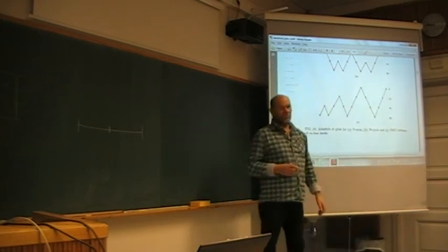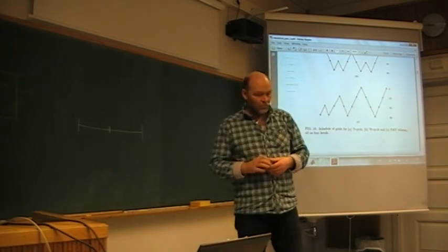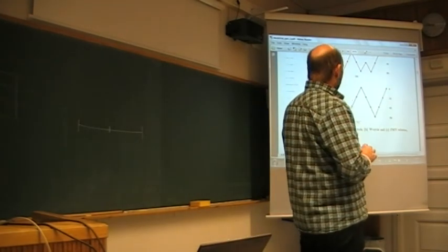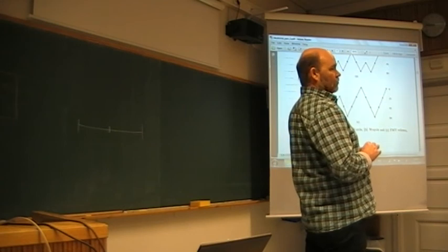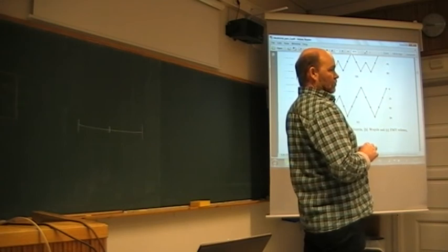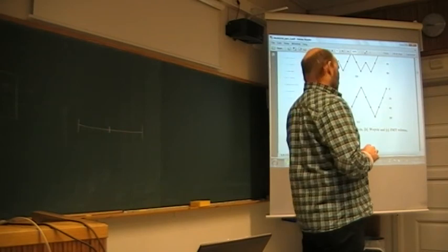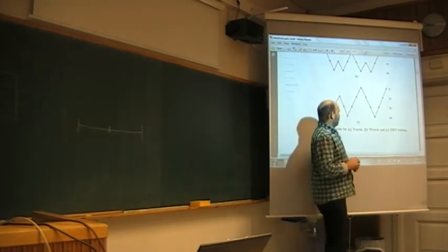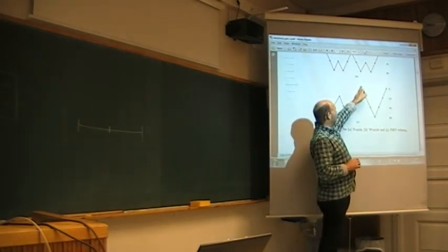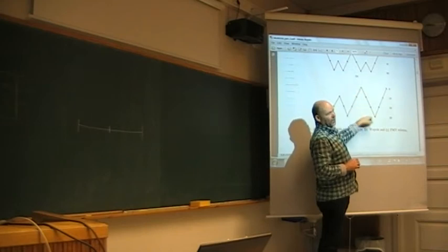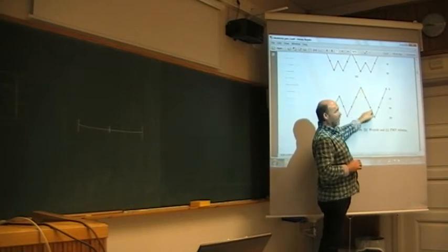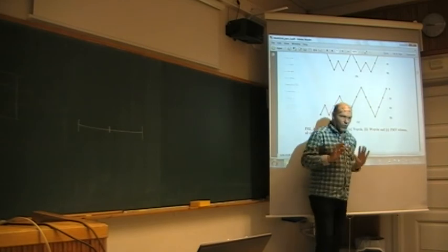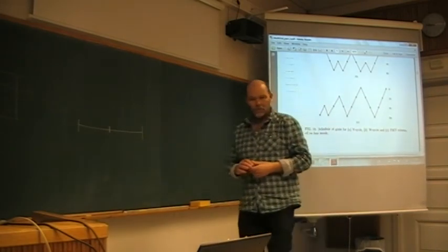Could you also, would it be quite similar if you would start on the finest, and then instead of going step by step, you just jump directly all the way down to the coarsest, and then you go with the full cycle up? Because then you have the original. It will actually not make any sense, because you can't represent any residual you have here on the coarse mesh in one jump. Then you have to go all the way anyway. So you begin normally with a simple V cycle. Much easier.